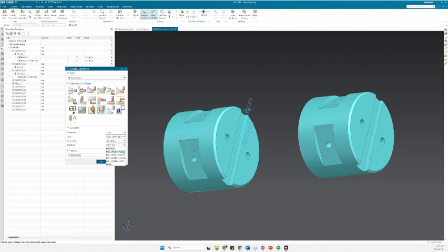Otherwise, you could also define the roughing and leave some material and then go back to the finishing. So I will just go to the finishing. Make sure that you are choosing these settings, and this is how we are deferring the post processor to give us the milling setting and not the turning setting. Then, for example, floor one, I can call the face slot, or the slot on the face, or I can just give it a number and then refer to this number. So one of them would be like this. Whatever looks better for you.